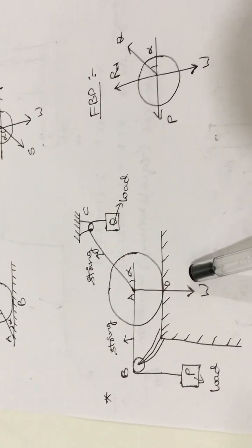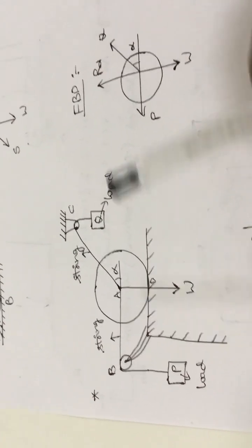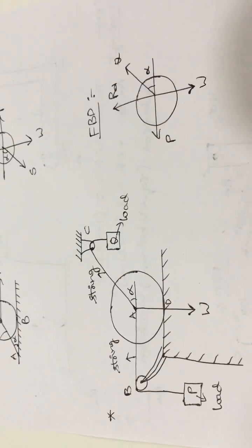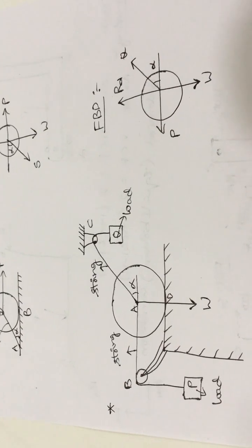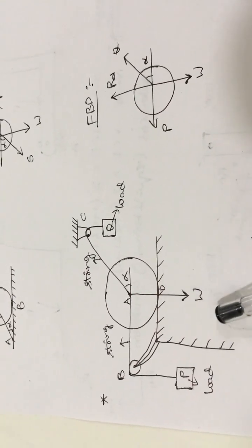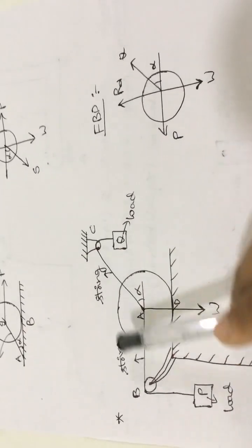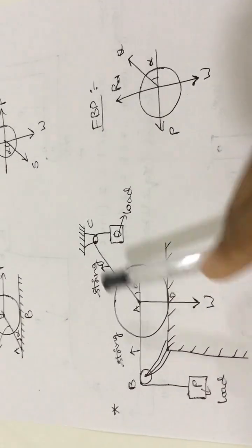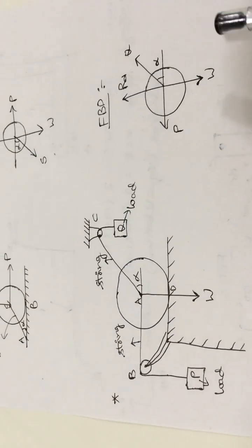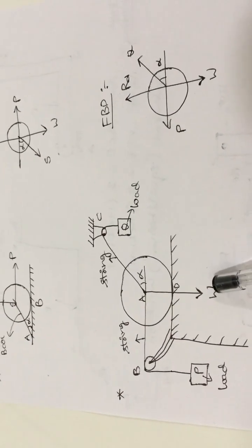So for this diagram we should draw the free body diagram. Here for this main diagram, W is the direct force. So you will get one direct force W, and then according to the question, here one more support is there. The dashed line is the indication for the support. So here first one, second one and third one, three supports are there. So from these three supports you will get the three reaction forces in the free body diagram, and one more direct force is there.